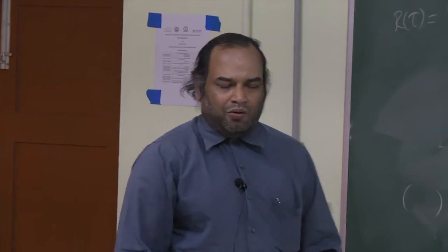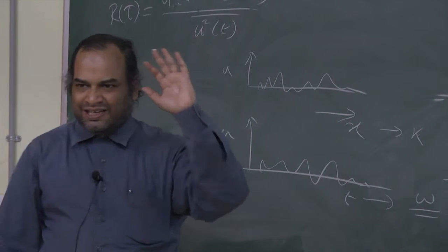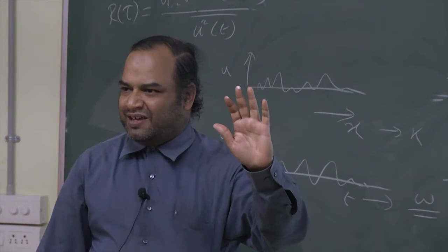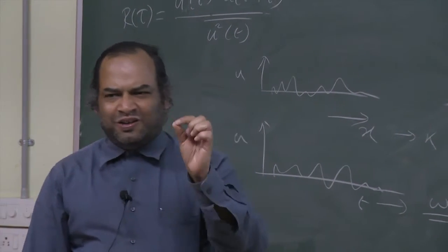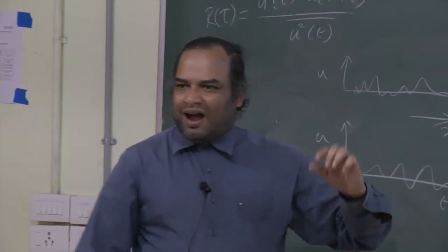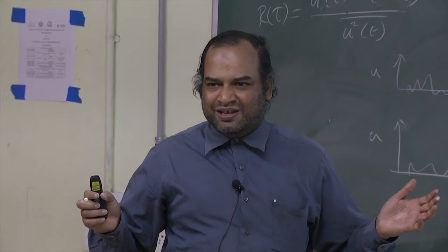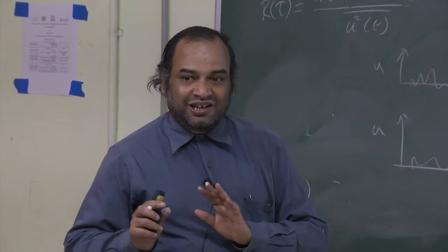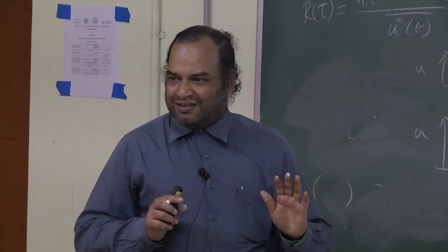Okay. Now, how do I get something like this? I could take an instantaneous picture of the flow with a PIV, for instance, particle image velocimetry, which in one shot will give me the velocity at different points in space. It doesn't give me any variation with time, of course. I'm talking about typical conventional low speed PIV, right? The typical 15 hertz kind of traditional PIVs.